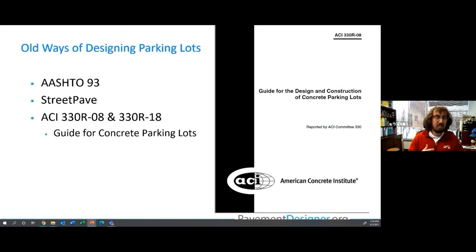So the different ways that you can design a parking lot that you may be familiar with are AASHTO 93, Street Pave, or ACI 330 design guides. So AASHTO 93 is more of a highway type design guide, and we'll talk about that when we go to streets and local roads, but it's not really something that trickles down well to parking lots.